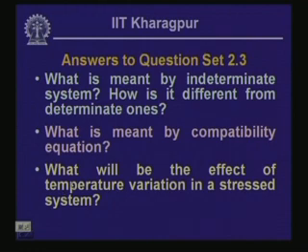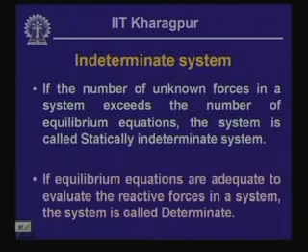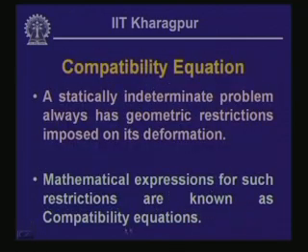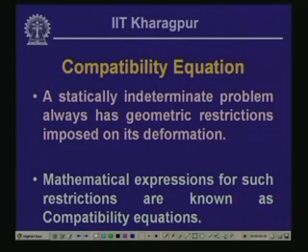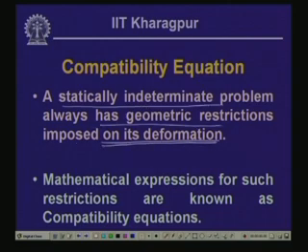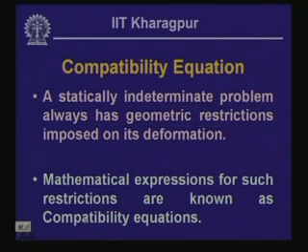Well, the second question posed was, what is meant by compatibility equation? Okay, let us look into this definition of compatibility. As we had seen last time, a statically indeterminate problem has geometric restrictions always imposed on its deformation, and the mathematical expression of such constraints or restrictions are known as the compatibility equation. Now, probably this can be made more clear through an example.